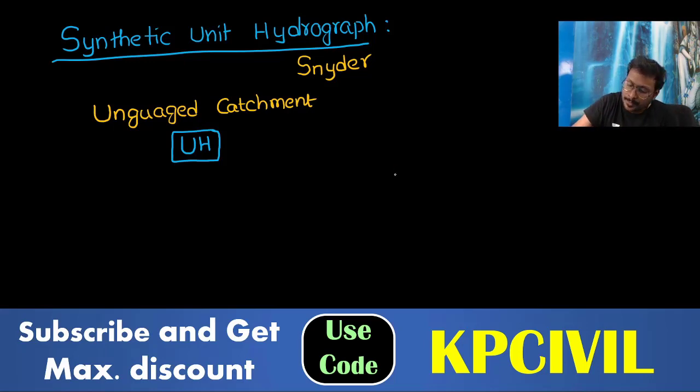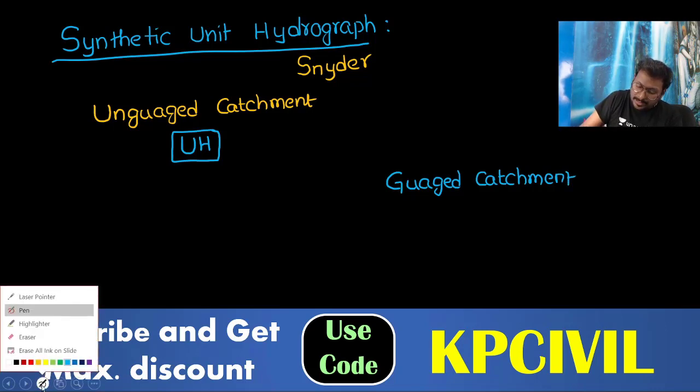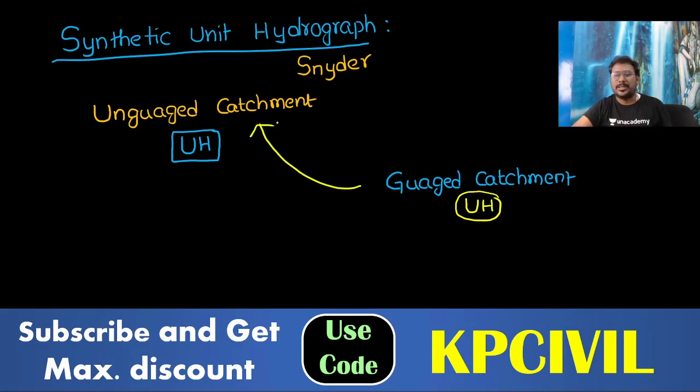Then what will you do? You take unit hydrograph data of a catchment that is geometrically, hydrologically and meteorologically similar, and compare it with the ungauged catchment. So you take the unit hydrograph data of the gauged catchment and plot a unit hydrograph for the ungauged catchment.